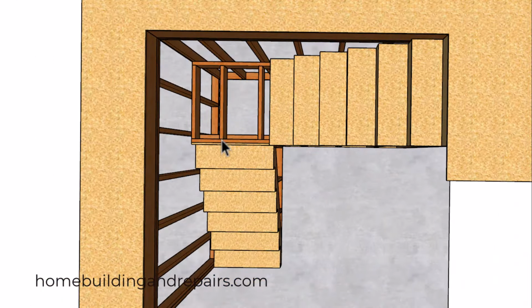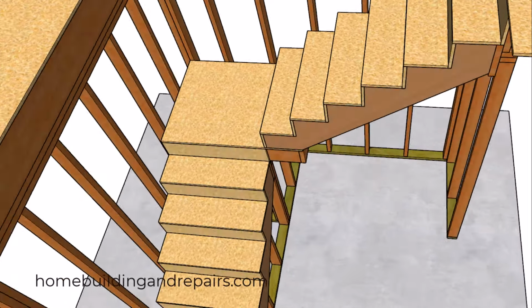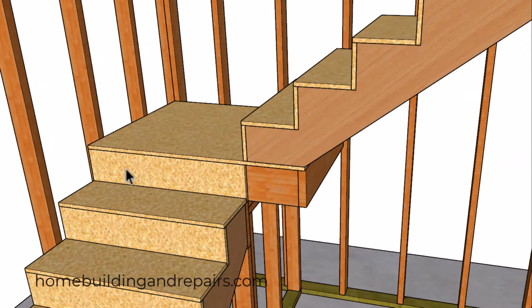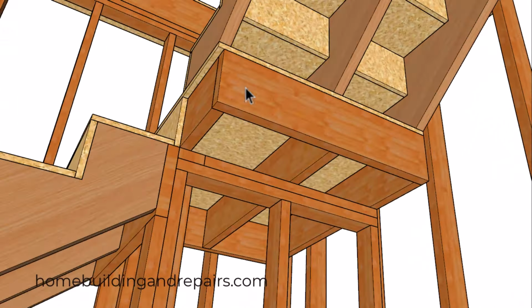then I would definitely recommend building the stairs like this. And of course you can run the joist in this direction here for this situation. And if you can't support it with a wall, but you can cantilever the joist over a wall, then this situation might work. So you're still going to be installing the stringers on top of the landing. The only difference here is that you've rotated the joist 90 degrees to run in this direction.